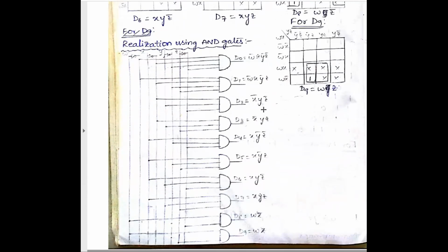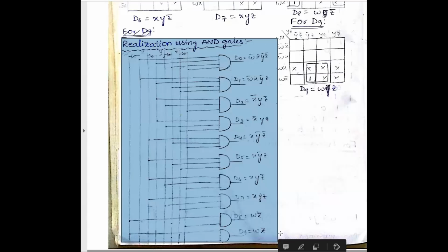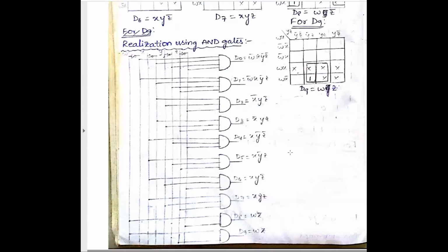We draw the BCD to decimal decoder logic circuit. The point here is that we are going to convert BCD to decimal. For that we have taken a logic table, and from that logic table we have written the output equations for D0 to D9. From that we have drawn the logic gates. The logic gate diagrams can use AND gates, NAND gates or NOR gates. Whatever the question they ask, we have to realize all the circuits in this fashion. You have to draw the circuit diagrams in this fashion. Okay.